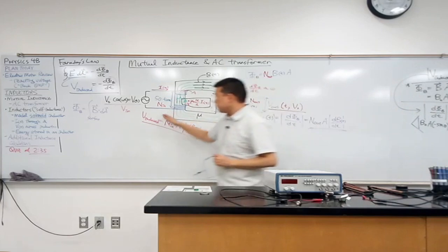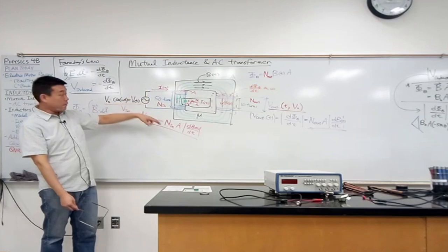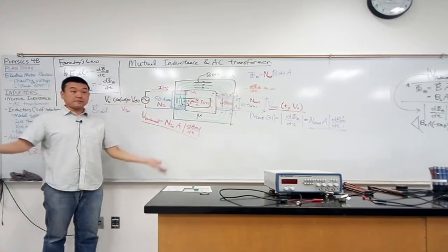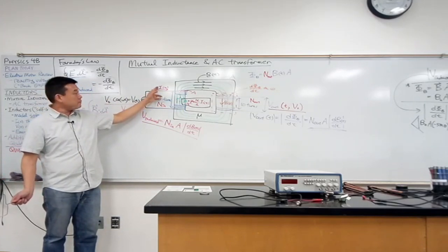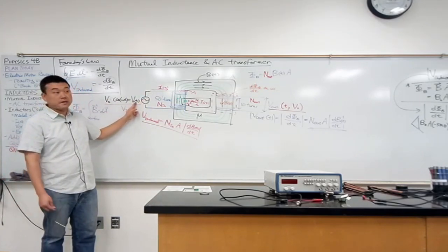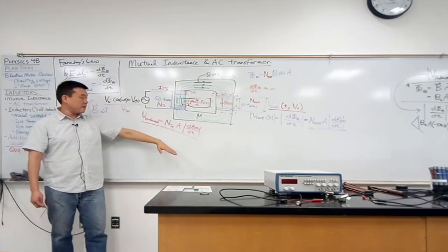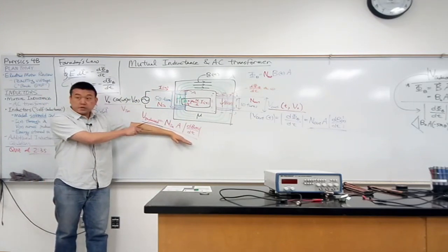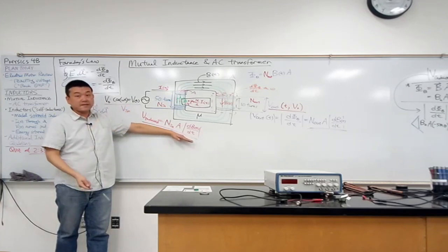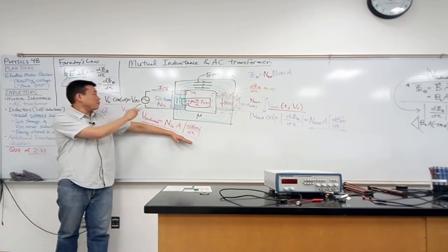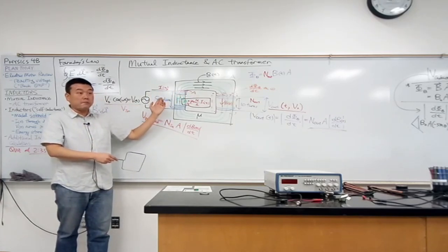It's the same idea here. It's the question of what is the amount of current when you apply a voltage. Well, if this is an ideal wire, then infinite, because resistance is 0. There's no limit to the current. But it turns out when you apply time-varying current, there is a limit. You don't get to push in an infinite amount of current. And the limiting thing is this: the induced voltage is what opposes the applied voltage. And at some kind of steady state, this induced voltage is equal to the applied voltage, so that no additional current is pushed into the coil or the other way around.